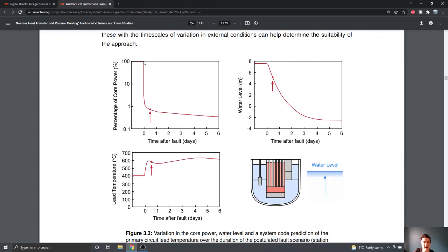And of course, what then happens is that the heat given off by the core drops rapidly. It drops at an extremely steep rate, which you can't quite see from the diagram here. But the important thing is that that heat drops down, and it comes to around 1%, at least for this model. We've assumed around 1% of what its initial thermal power was when it was undergoing nuclear fission.